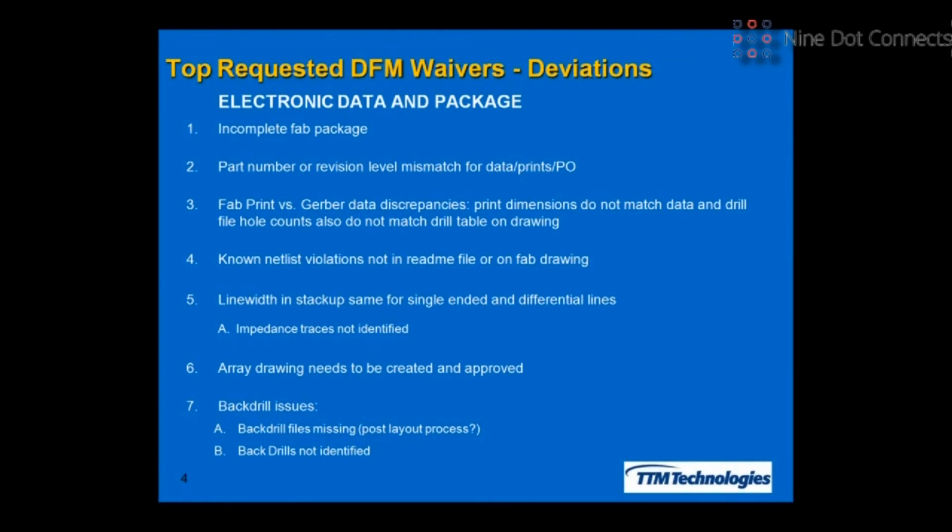When I talk to a lot of the engineers, their layout tool is actually done after the fact, and either they don't push the button, or they don't run the script, or whatever they do, the files are just not there, and they're not supplied. So we always have to push back and say, hey, we need the back drill files, because they're just not contained in the package, or they're not identified, and that could be a bunch of different things. But this is a thing that we see pretty routinely.